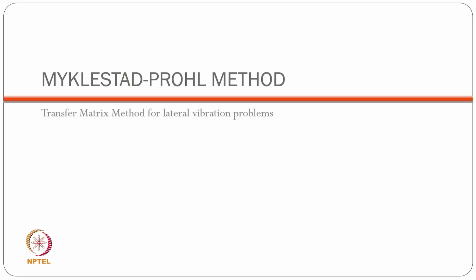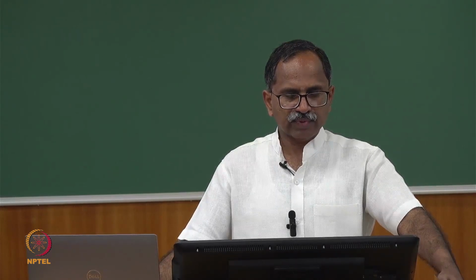So, longitudinal vibrations of a propeller shaft or that of a push rod, all of that can be analyzed conveniently using the same approach which we have discussed as the Holzer method. Okay. So, primarily it was designed for torsional vibration problems, but the same can be easily extended, in the sense reformulated, for longitudinal vibration.